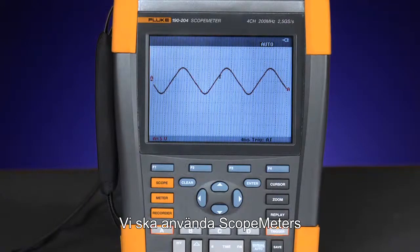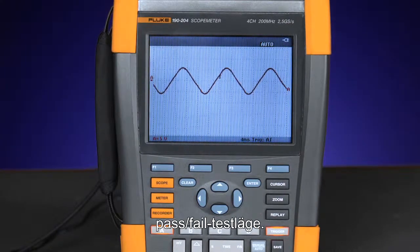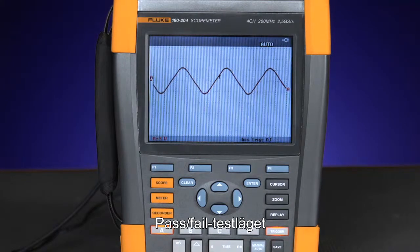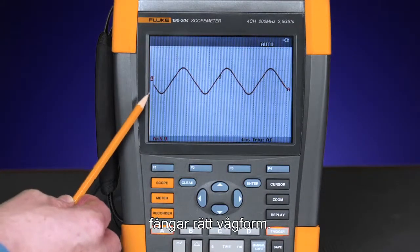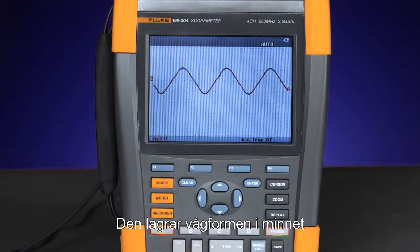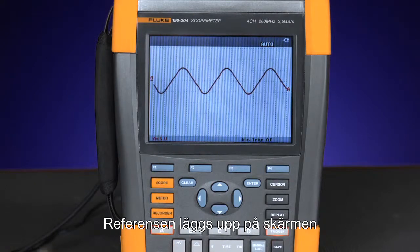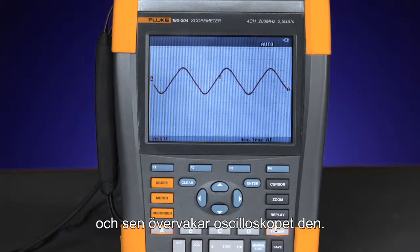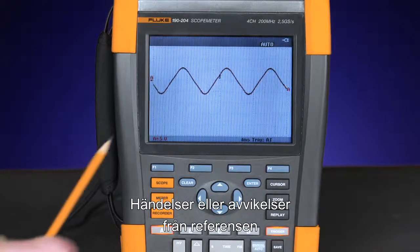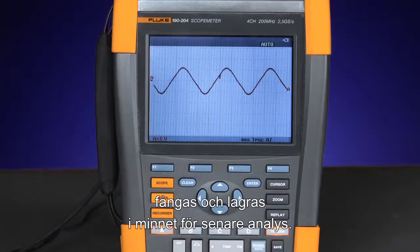To get to the root of the problem, we're going to use the ScopeMeter's pass-fail testing mode. The pass-fail testing mode has the ability to capture the waveform in a known good state. It then stores the waveform into memory to use as a reference envelope. The envelope is created on the screen, and then the oscilloscope continues monitoring. Any event or anomaly that goes outside of that predefined envelope will be captured and stored in memory for you